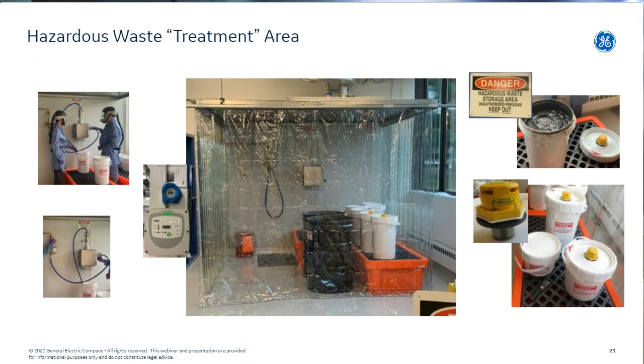Here is also a good best-practice example of how we do it at GE. For filter passivation, we take the filters out of our wet filters, we clean them, we put the sludge into drums, and then we skim the water from these drums and have the sludge in specific waste containers that we can dispose of. You can see some of our colleagues there in fall protection and in a ventilated area, so that we make sure we do not generate any specific hazard or reactivity.